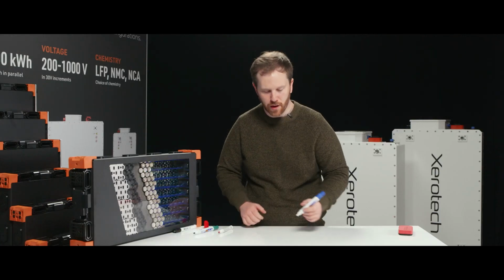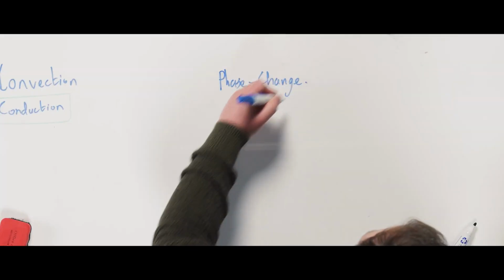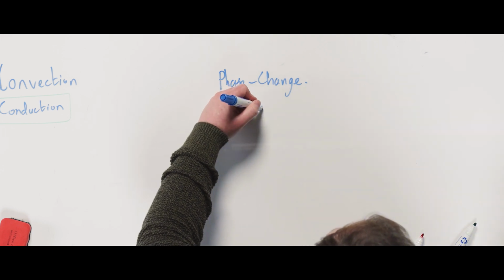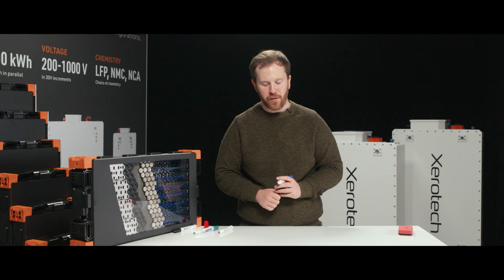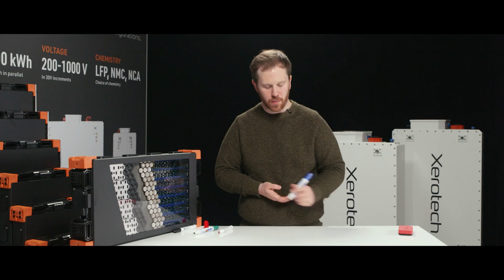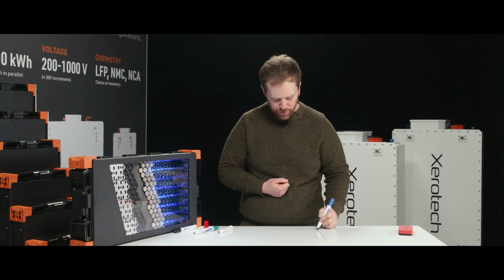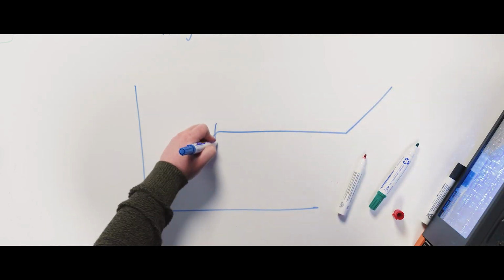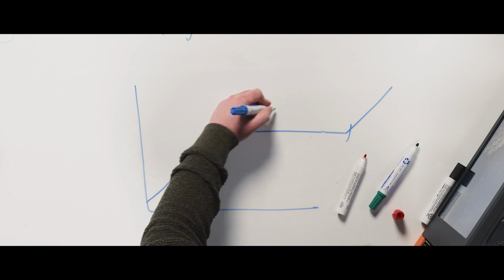So we did speak about 3 main types of cooling: air cooling, direct liquid cooling, and indirect liquid cooling. There are a couple of other more exotic solutions, but they're not very prevalent on the market out there. You've got something called phase change systems, and then you'll also have refrigerant, which are a combination of these. So basically the phase change systems rely on that latent heat that we spoke about before, where for the example of water, it would go up like this, stay flat for a very long time before it heats in temperature again as you go through this phase transition.